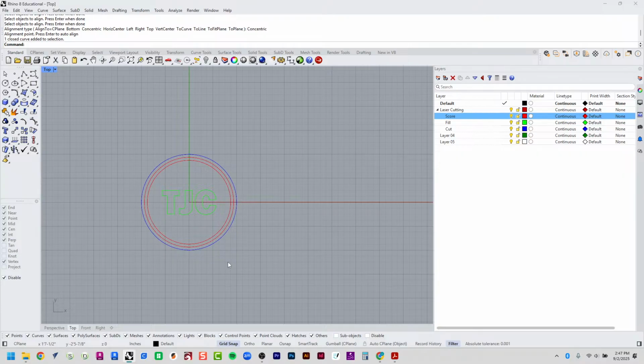The next coaster I'm going to create is for CNC purposes. So I'm going to change layer 4's name to CNC. I'm going to make sure that that layer is active by moving that check mark in this column to that row, CNC. All we need to do is click in that area where that column and that row align, and now CNC has a check mark next to it, and the word CNC is bold. That means that layer is current.